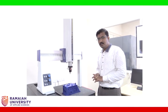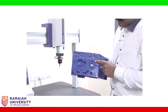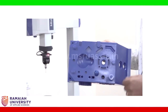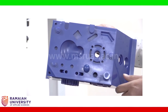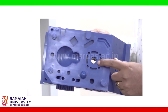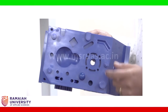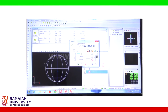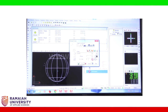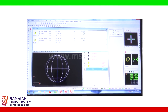Now let us do one inspection demonstration. You can see the different configurations here, different cutouts here, and there is a hole, a through hole, which is measuring 20 mm, and the tolerance is plus or minus 0.1 mm. Now let us measure this circle and find out what is the true dimension of the circle. Now I am choosing the circle option, and circle name is circle number 5. We are choosing number of points as 4, and now once I give OK, you can see the circle symbol here, and the CMM is waiting for the first coordinate point.